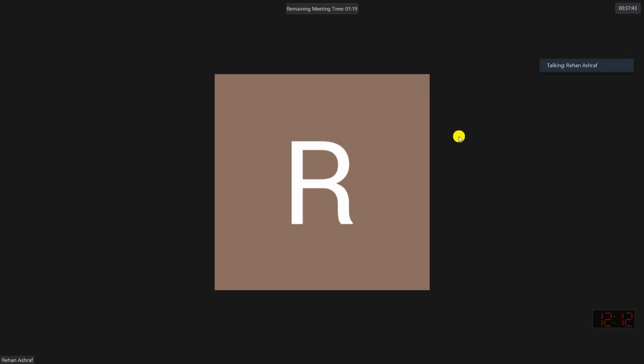Maybe that was your question, but to give you an example, I can tell you that let's say consider any slab panel of our classroom, of our drawing hall. It has longer slab panels, right? Now you may say that in the whole classroom it has walls all around, so you can have a bigger slab panel. But this much big slab panel would be too much heavy, so that's why beams are provided, right?